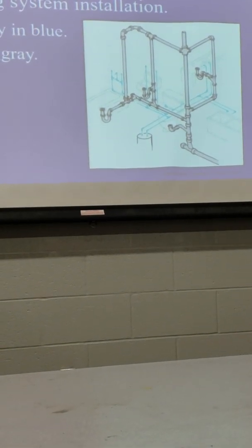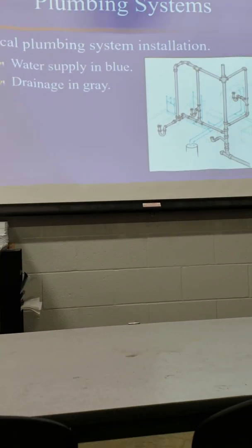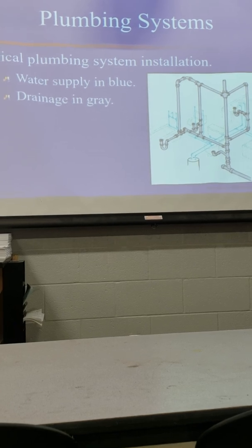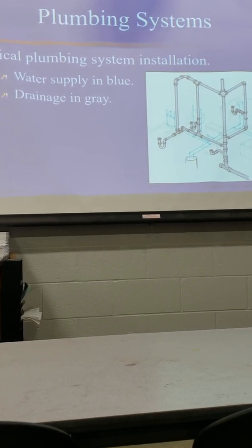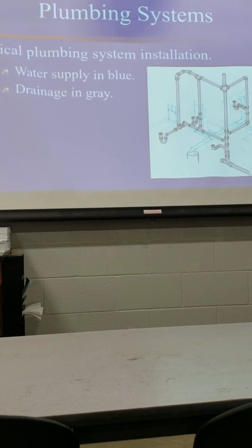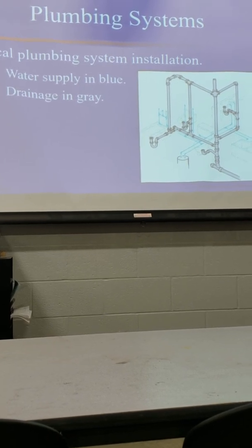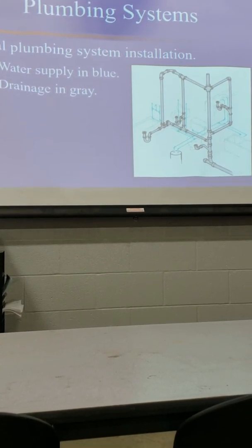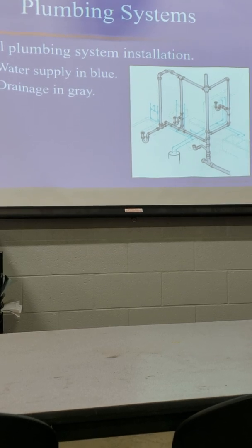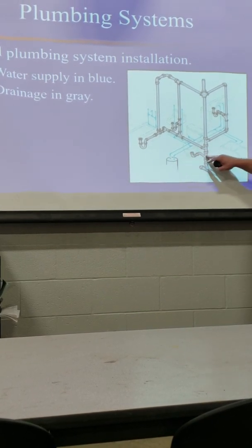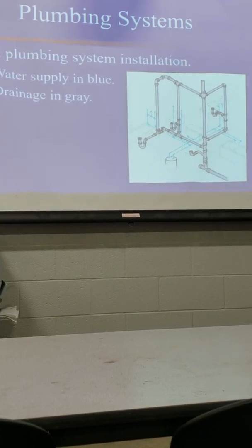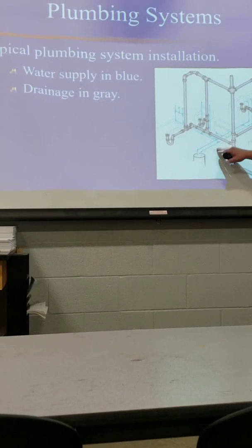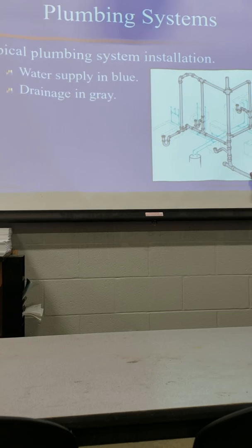Now, I know you know nothing about it, does that picture look right? I told you it's wrong, but what about that picture would be wrong? Should it have another vent pipe and two vents? No, you can do all that in one single vent. It's right here on the water closet. Alright, water closet connects, comes over, vents up, drains down.